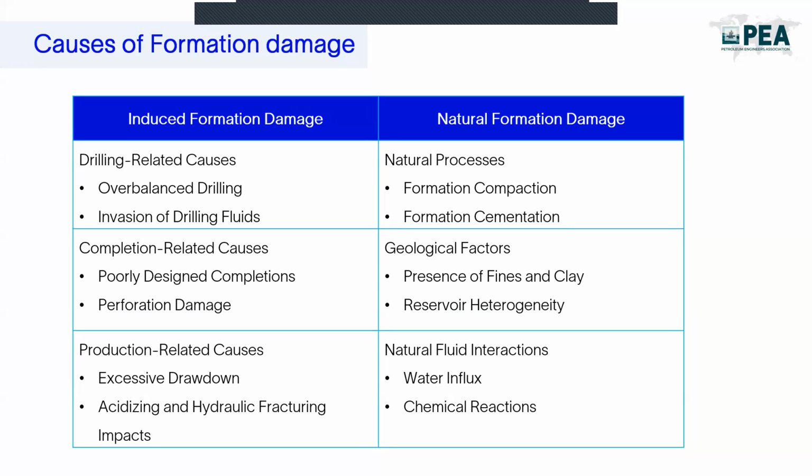And then another thing: if there is insufficient penetration, so if the perforations were not sufficiently penetrated to bypass the drilling damage, the perforation will not help us start production.